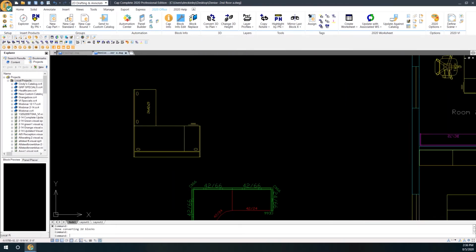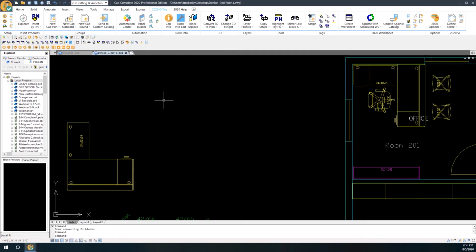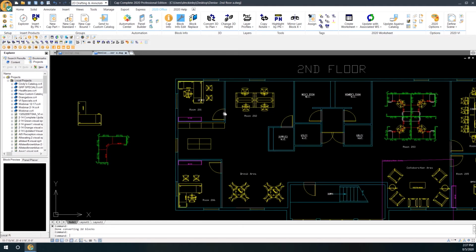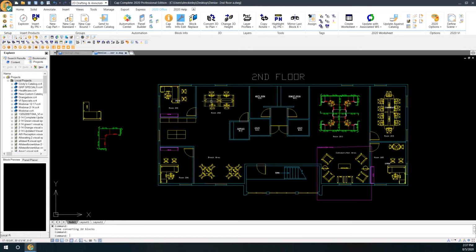Tags, just so you know, everything for the most part has a tag when you bring it in. If you don't like that tag, there are tagging tools that you can use to append to the tags or change them. You have the ability to assign additional tags, I believe up to four tags. Those can be visible or not visible. They're very helpful if I'm working in a large project and I want to separate furniture by locations, maybe for budgeting purposes, so you can have all these extra tags available. So as I said, it's high level, I just want to make sure you understand.